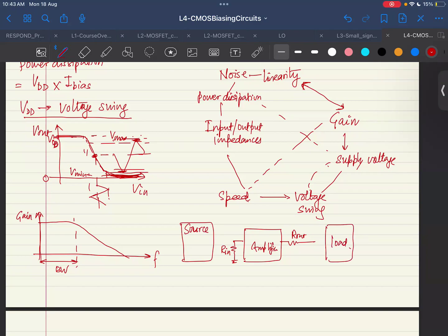And typically the source resistance we can model, in voltage mode, with a source resistance Rs like this, which is a Vs. And the load we can model, let's say, with a simple resistive load, for example, here, RL, right? Which is your Vout. And this is your Vin dash, and this is your Vout dash, right? Which is coming from the amplifier. So we know the relation between Vout dash and Vin dash, which is just Av times Vin dash, if we assume it is a linear thing.